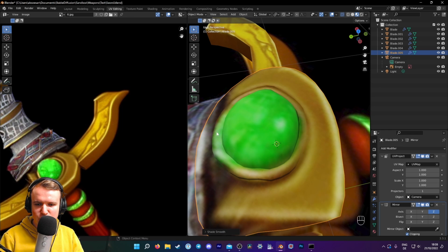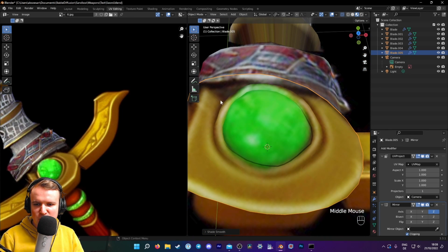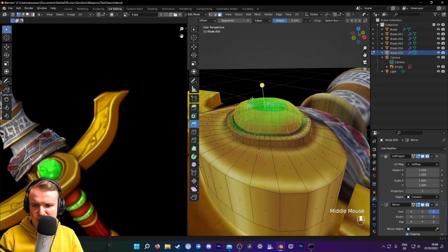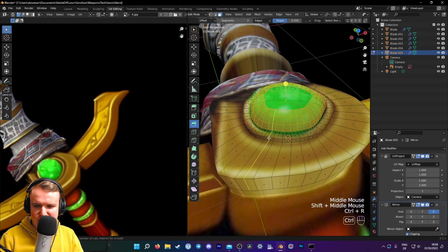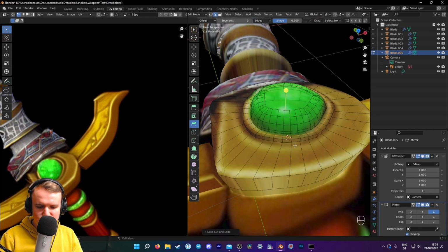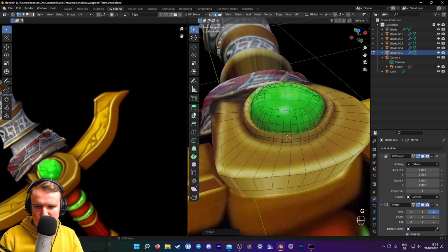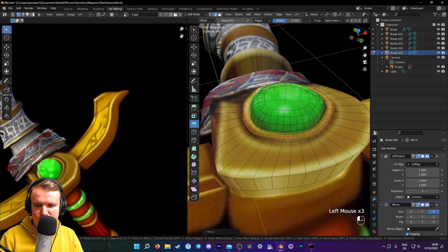We obviously have a little green there and something, but we can texture paint that later. And I'm also going to bevel this round part here because I don't like how many corners it has. It's very edgy. So I'm going to Control R this and raise it up a little. And also bevel, but with just 2 segments should be plenty.